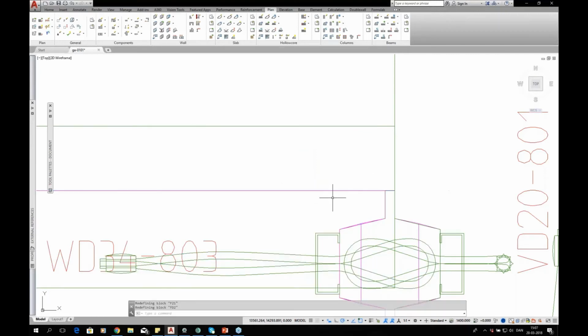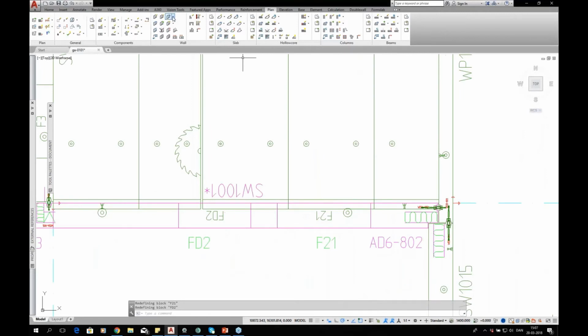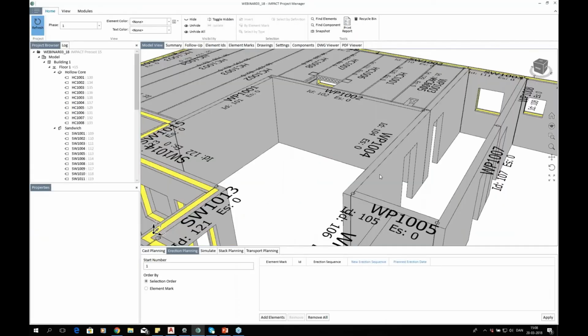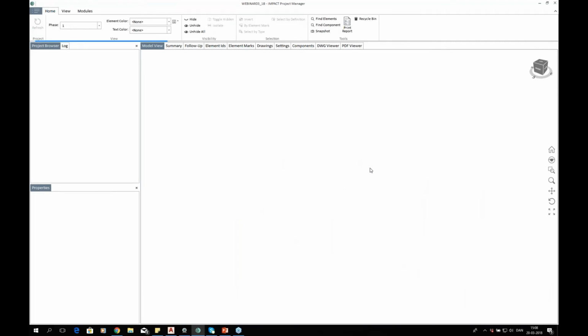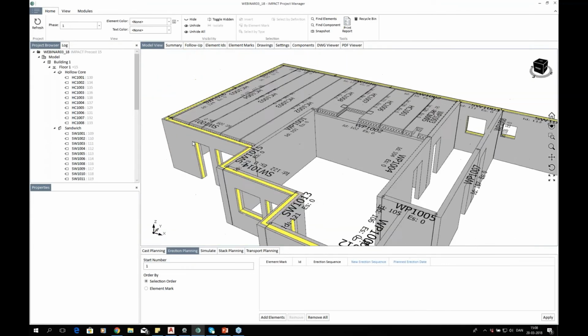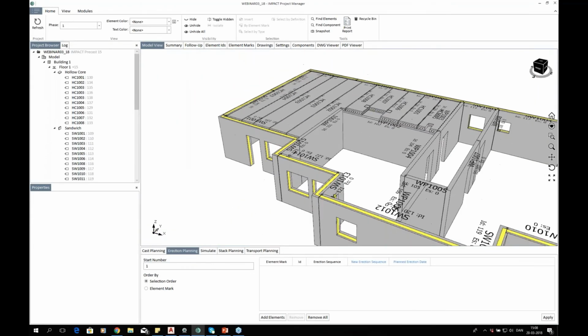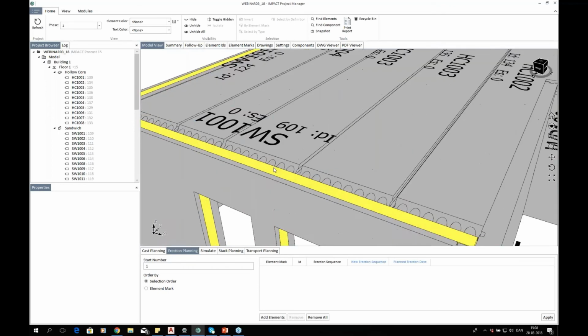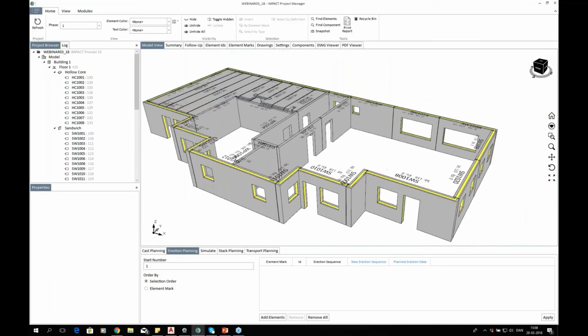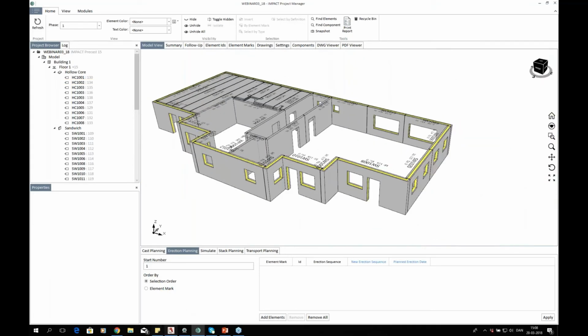Of course, I want to update the placing of lift and bracing anchors again. And of course, I want to save this element again. There we go. So looking at our project manager now, we have the hollow cores lying just fine here. We have them lying just fine on this panel as well. So that actually means that, for my part here, these hollow cores are designed and finished as well.